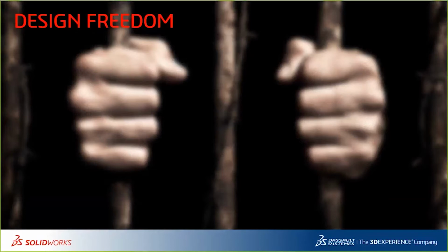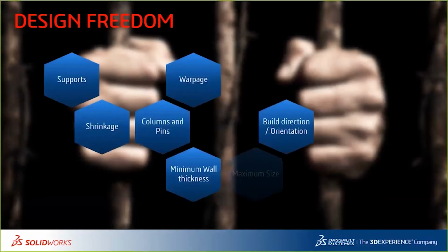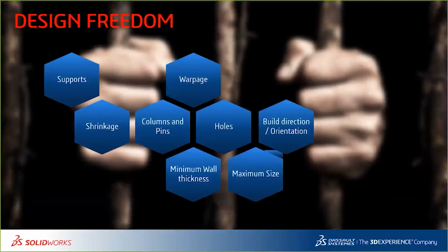So, with all this talk about design freedom, can we just design whatever we want when it comes to 3D printing technology? Well, unfortunately not. When it comes to 3D printed parts, we still have to consider things like supports, the possibility of shrinkage, warpage, how our holes are being positioned and designed, what our minimum wall thicknesses are, because it's being driven by the specifications of our 3D printers.